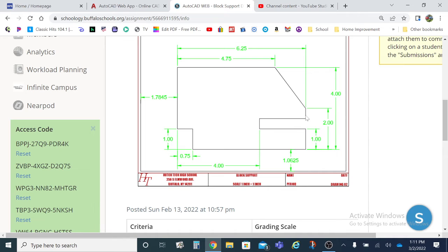Now, somebody's going to say, well, how do you know it's not 0.6 and 0.4? The reason I'm going to say that it's probably not that is just look at my dimensions. The biggest difference between any dimension is 0.25 units. So if I look over here, just by guesstimation, does this look any different than this by 0.25 units? And the answer is no. Does this one look like it's 3/4 of an inch and this one look like it's 1/4 inch? No, they look pretty balanced. So we're going to use that information.